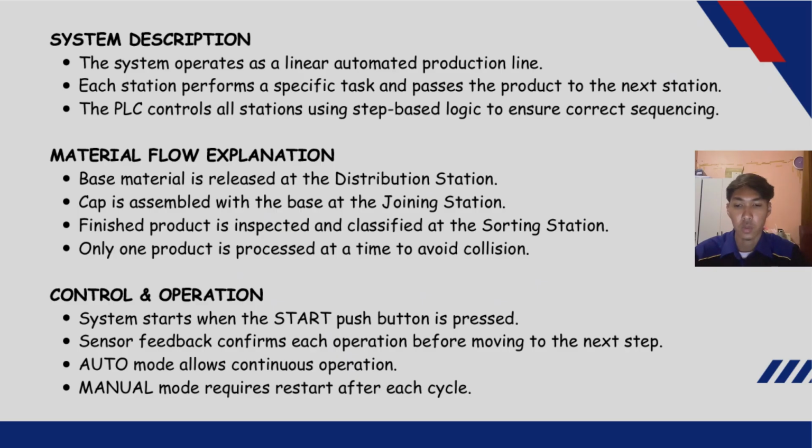And the next is control and operation. The system starts when the start button is pressed, and the sensor feedback confirms each operation before moving to the next step. Auto mode allows continuous operation, and manual mode requires restart after each cycle.